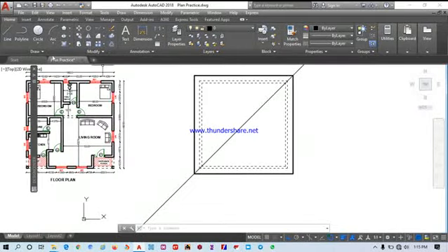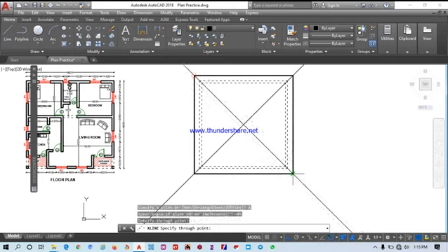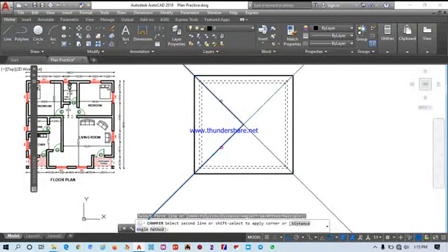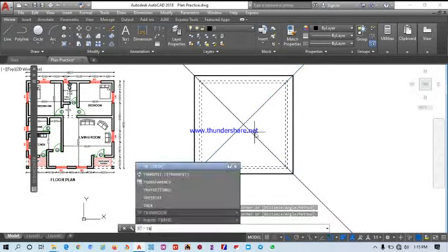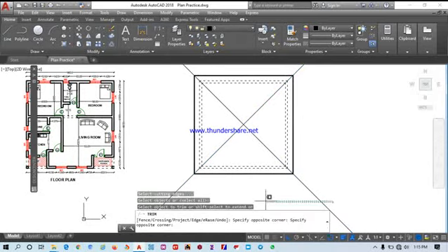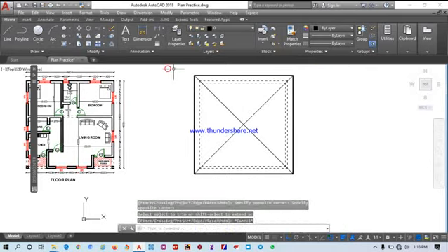So then let's go to construction line again, or you just press your space bar, you right click, angle 45 will not work. So instead of calculating the angle that will suit this area perfectly, since we are working on 45, I will just use minus 45, which is the opposite. I will click on the two edges. The next is to chamfer. I'll click on my chamfer. Click on the two edges. Click on chamfer again. Click on the two edges. Then we are there. So I'll trim off this excess. I'll trim off this one that is not useful. So trim it off. So here we go.